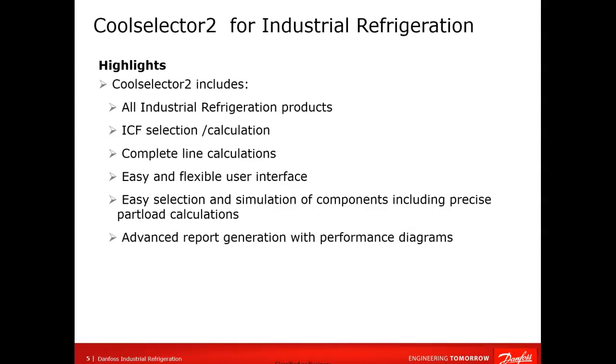The interesting thing is that you can make complete line calculations, meaning not only the performance of one component, one valve for example, but we can simulate the whole line performance including piping, including additional pressure losses. It's a very intuitive and easy interface, so a new user can get on track quickly.